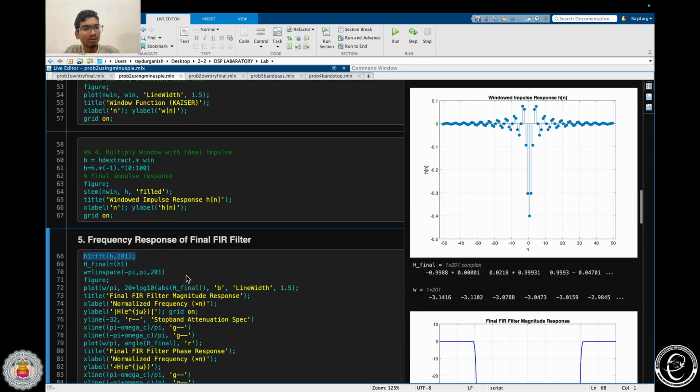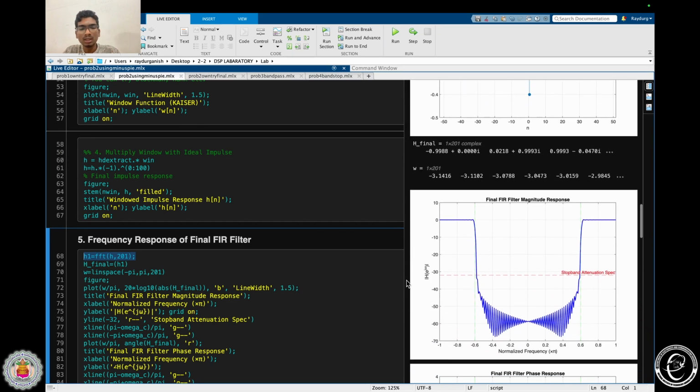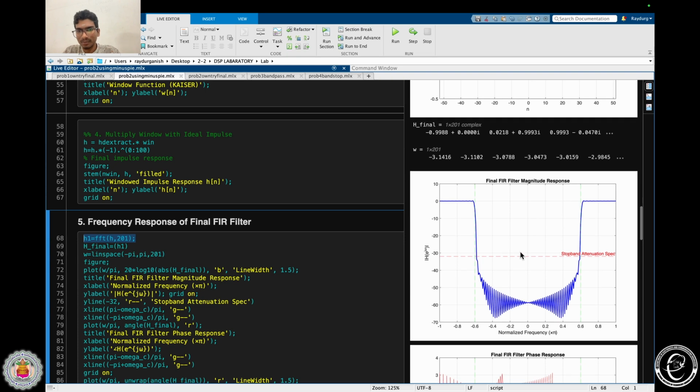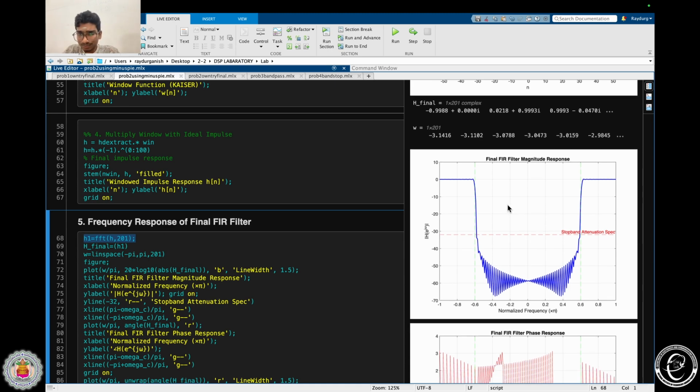Again, you will use the FFT to calculate the digital frequency response and the magnitude. And here you can see, before it was like this, it was allowing. Now I have flipped pi radians, so now it is like this. So here it is allowing, and in between, at the low frequencies, it is highly attenuating. So this corresponds to the high pass filter.